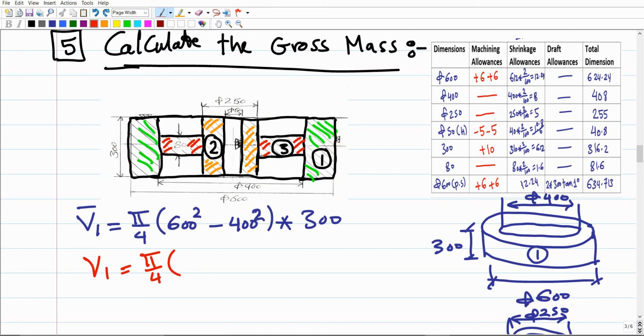I won't ask you to accurately calculate the conical shape, because this is going to be a conical shape with a cut top. The top part of the conical shape will be cut. I won't ask you to do accurate calculation to come up with the exact volume of this conical shape. Just give an approximate calculation, and this is even what we are doing practically. You can take the average of these two numbers, because the 600 has two values. It means that this surface will be a tapered surface, a conical shape. It means that this ring won't be cylindrical, it would have some conical shape, right?